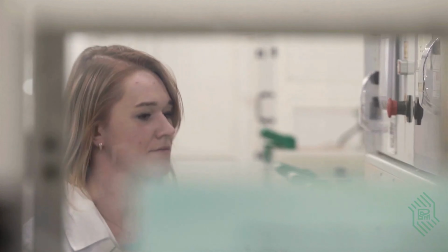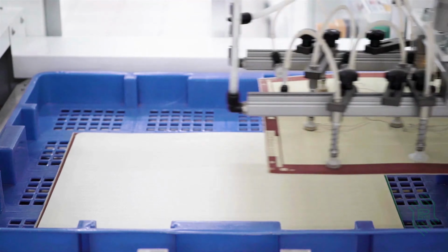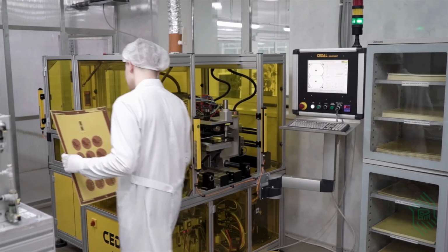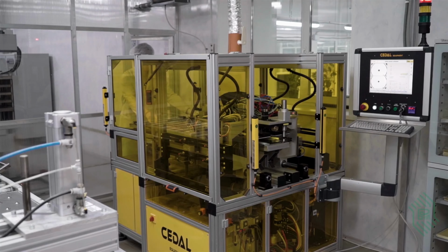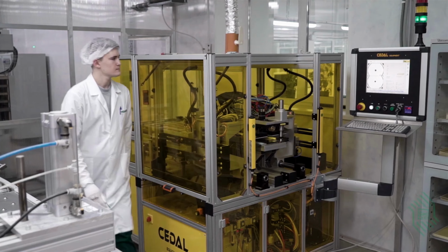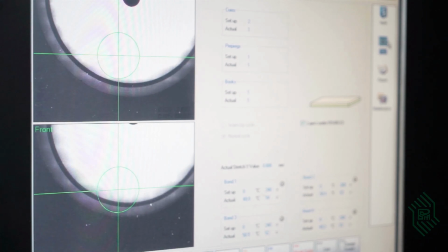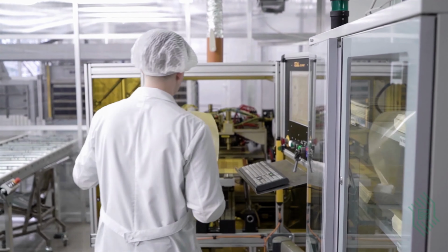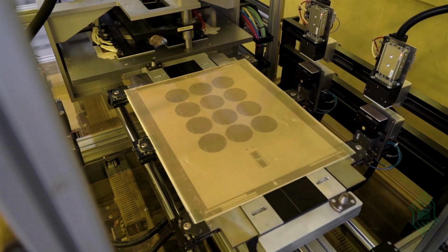Before bonding, an organic complex is deposited on the cleaned copper surface to develop the surface and improve adhesion. For positioning the inner layers between each other, the bonding machine is used. After assembly, the stack of inner layers is bonded together by a prepreg using induction heating.